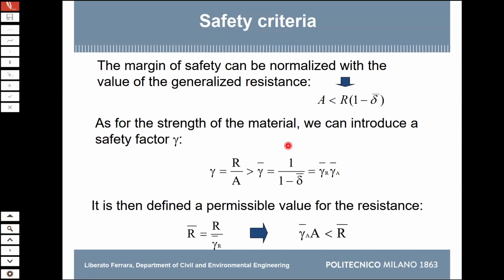That means. Where did that number come from? You hardly can tell it. Well, there are some social models and so on. For example, the Eurocode, the European codes, allows that if you have larger spans, you can reduce by a certain factor the live load.